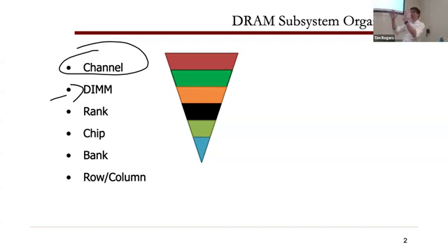Okay, and then the memory controller, the channel, is the thing that's sort of perturbing all those lines and getting you the data. The memory controller has to know how that chip operates. That's why we have standards, right? That's what JEDEC is for. That's why there's DDR3, DDR4, because I want Micron to go build DIMMs that adhere to one timing standard, and I want Intel or NVIDIA to be able to build chips that have a memory controller that knows how to use that memory standard, okay?